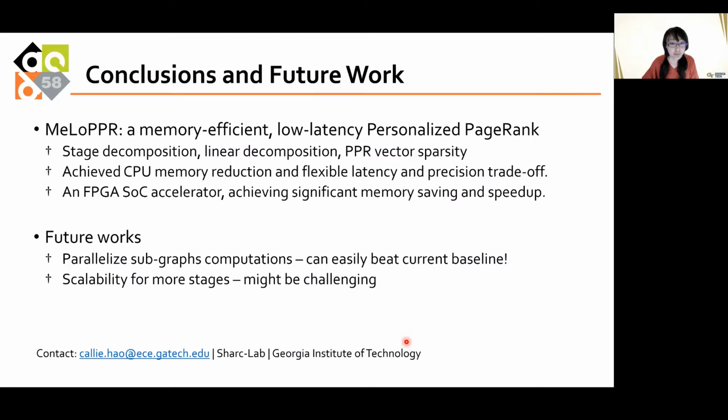So this is all about this work. To briefly conclude, we discussed a memory-efficient, low-latency, personalized PageRank algorithm, which is achieved through stage decomposition, linear decomposition, and PPR vector sparsity. We also demonstrated the CPU memory reduction with a flexible latency and precision trade-off, and we also discussed an FPGA accelerator.